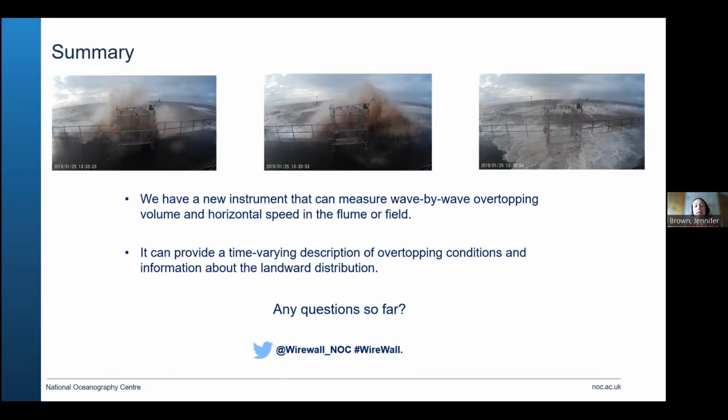People are also starting to analyse satellite images to look at beach levels as well. But because of cloud cover and issues with when the satellite passes and how frequently it passes, they often have to apply averaging processes. So you would get probably an average beach profile every couple of weeks. So you still might not get that beach level just before a storm impacts. I think at the minute they're mainly looking at seasonal changes within beach level using satellite data.